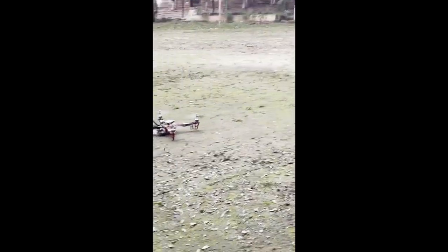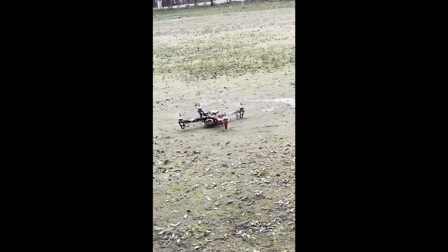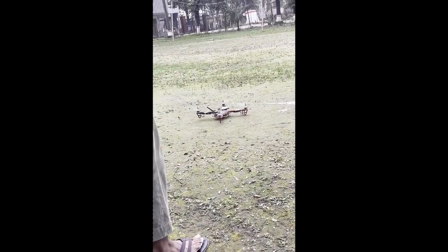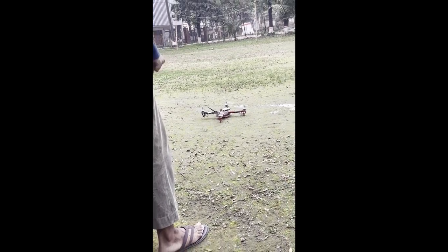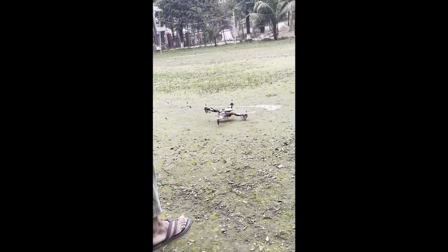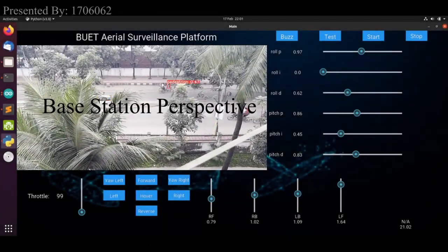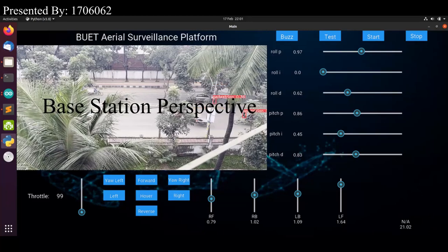The key reason behind this was that the arms were vibrating too much and the gyroscope was not generating steady voltage. Also, the throttle speed in the trials was not enough to lift the heavy weight of the drone. This is another reason why we could not sustain a camera on it to take video clips, as it would further cause imbalance.